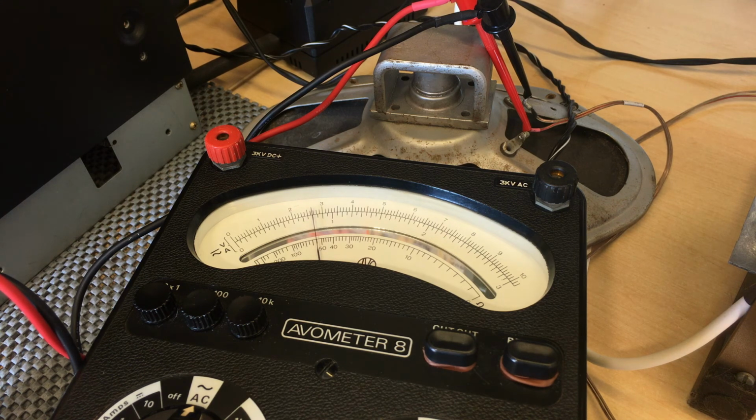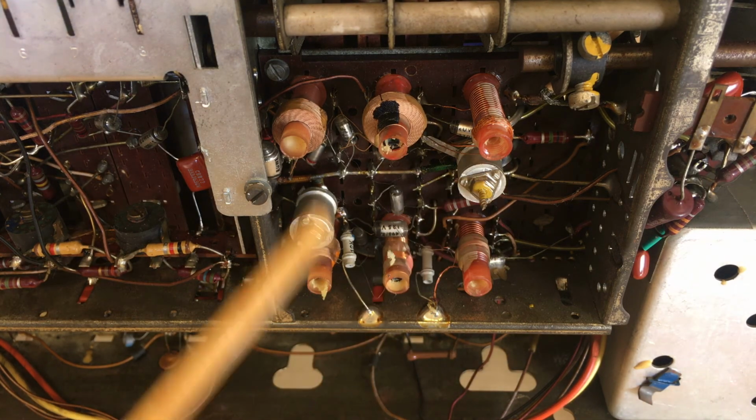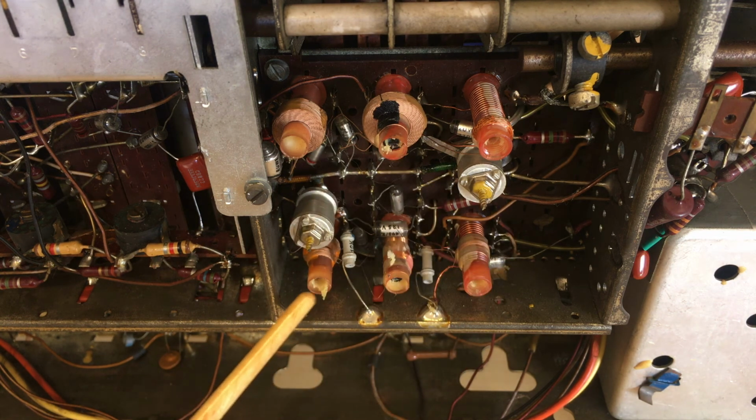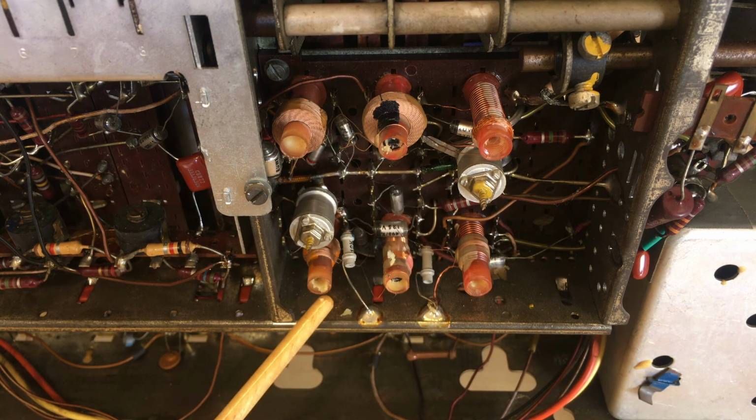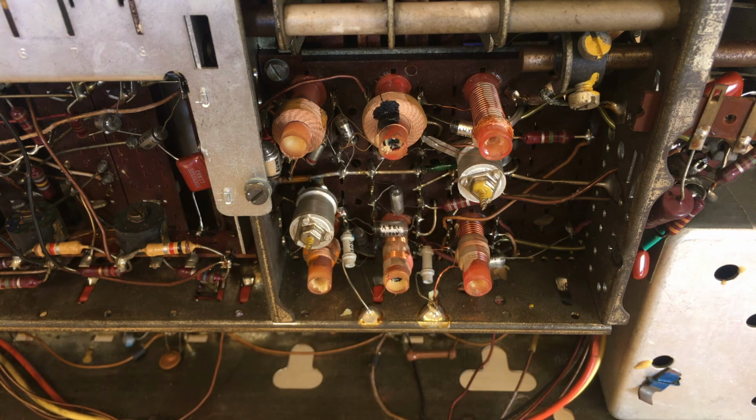Now let's do the antenna coil. There's our peak. Brilliant. So now we're done with these dreaded coils. They're always a bit finicky. They have wax in them, and they shouldn't have been very far off, but with age and component changes and so on, it does make a difference.